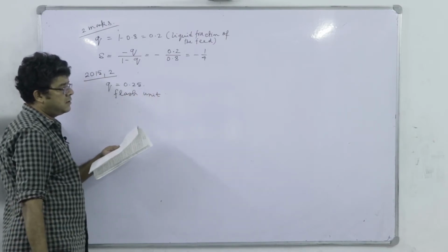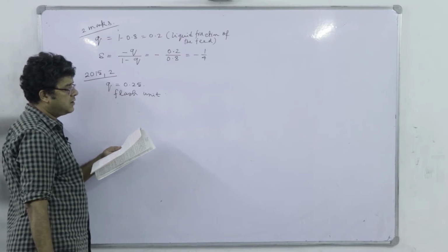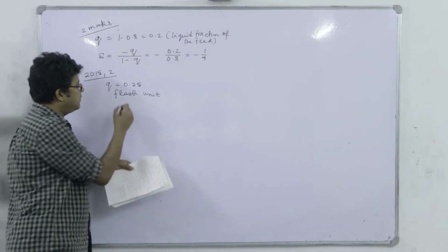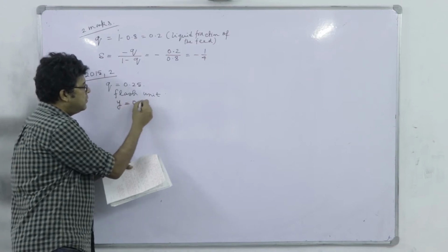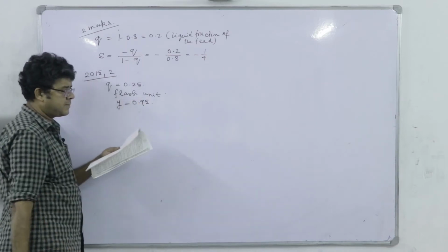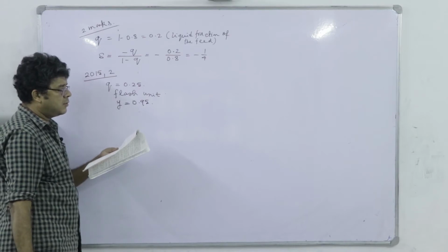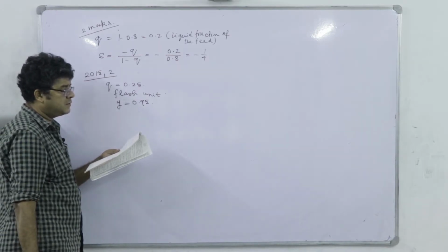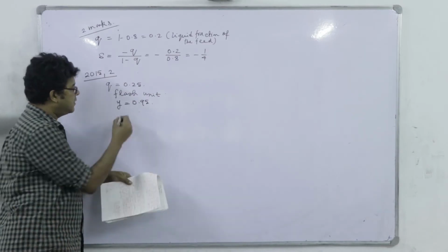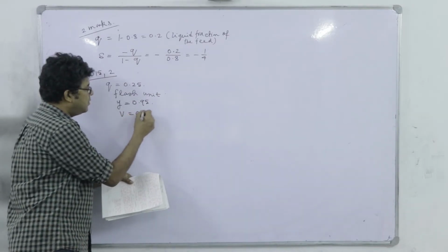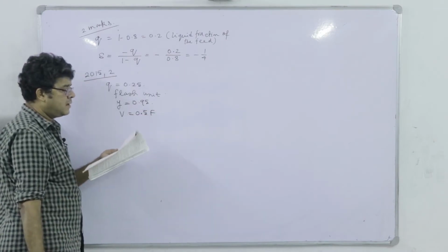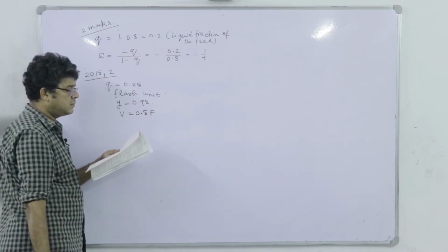The mole fraction of more volatile component in the distillate product is 0.95. So, y equal to 0.95. The molar flow rate of distillate is 50% of the feed flow rate. So, V equal to 0.5 F, and McCabe-Thiele method can be used.